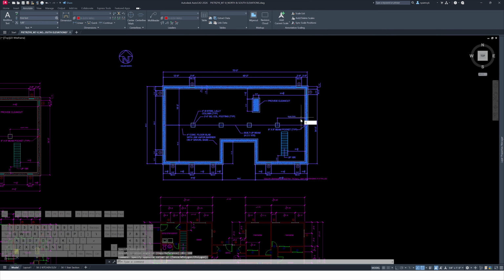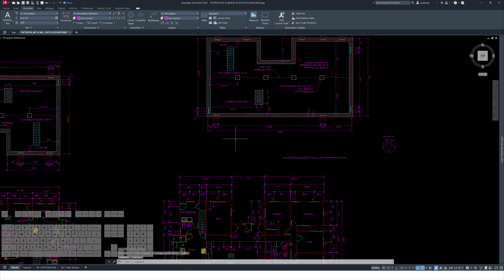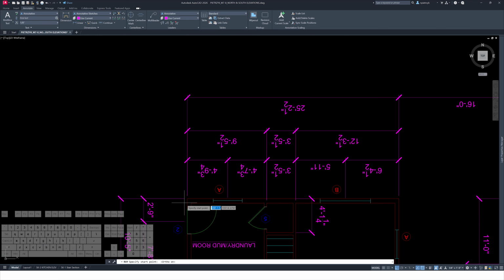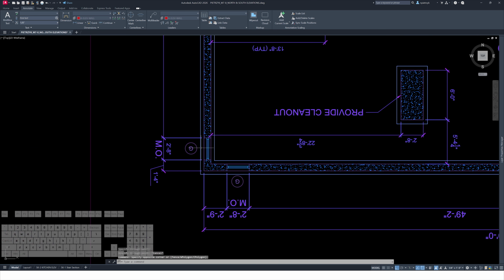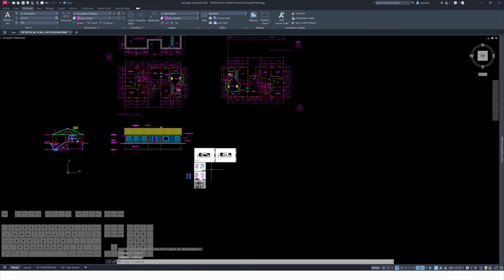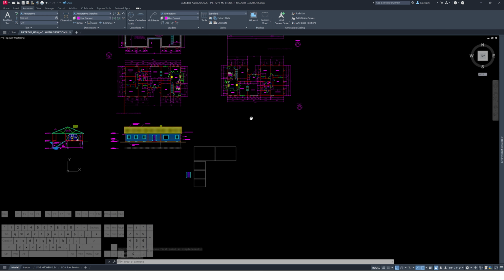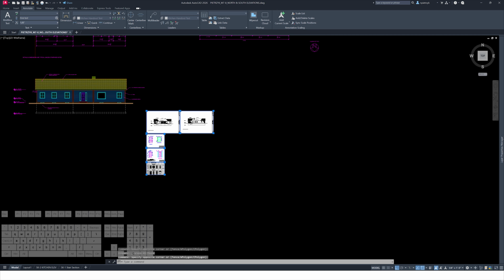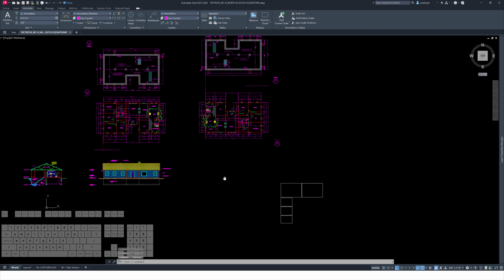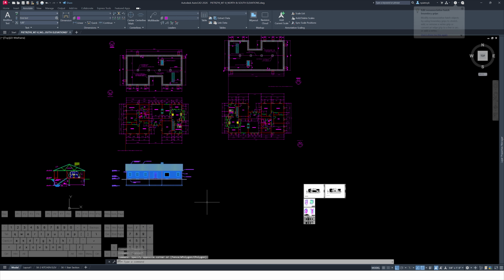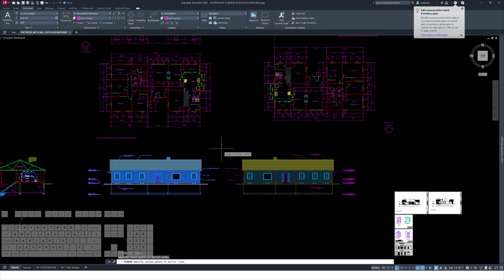Same thing with this one. And I'm going to do my F8, and again, I'm going to line this up. There's only 2 of these vents I need to do down here. And I'm going to move these guys. First, I'm going to delete that. I'm going to move these images here so I have them still. I'll keep all this junk here. And what I'm going to do here is I'm going to take all of this, do a mirror command. So it looks like this.